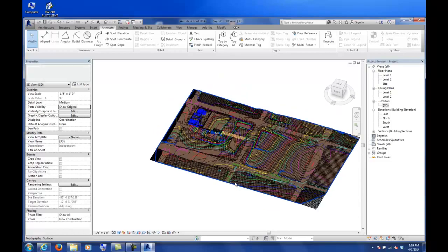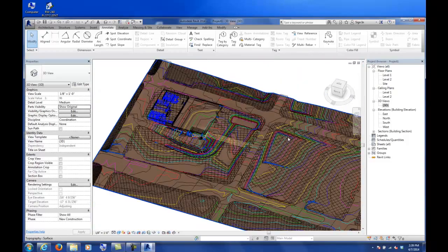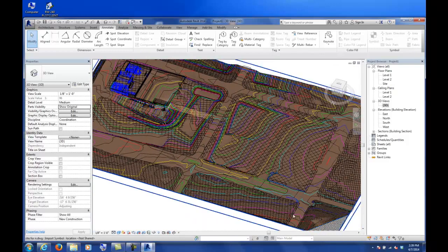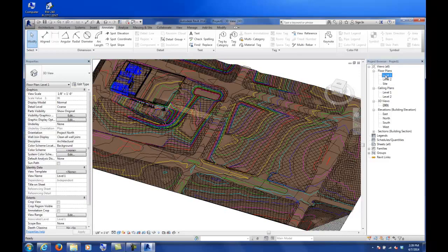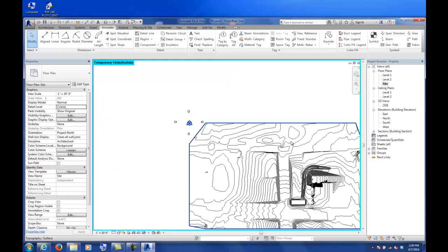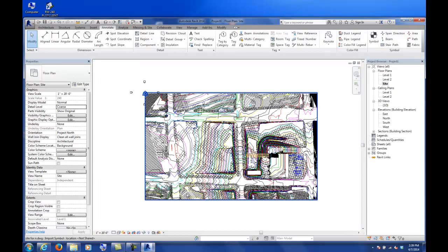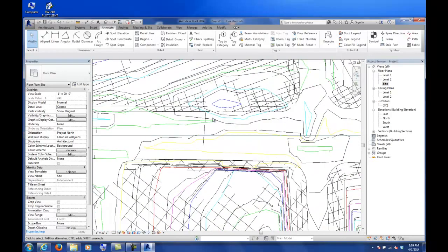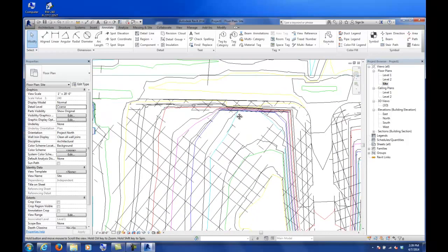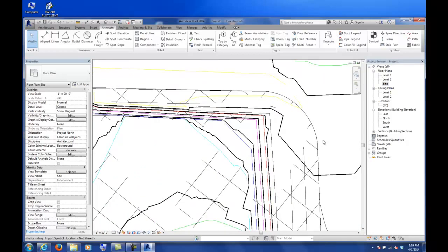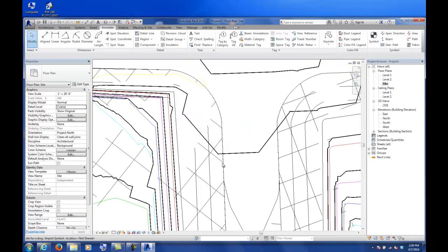Seems pretty self-explanatory. Now, once you have this topography surface, we can do a couple things, such as start to divide it up into different parts so that you could delineate what's road versus what's dirt, what's grass, or other materials. And to do that, it's best to go into, let's say, a site plan. I'm going to turn back on that DWG file. And it looks like I've got at least some outlines relative to maybe some roads.